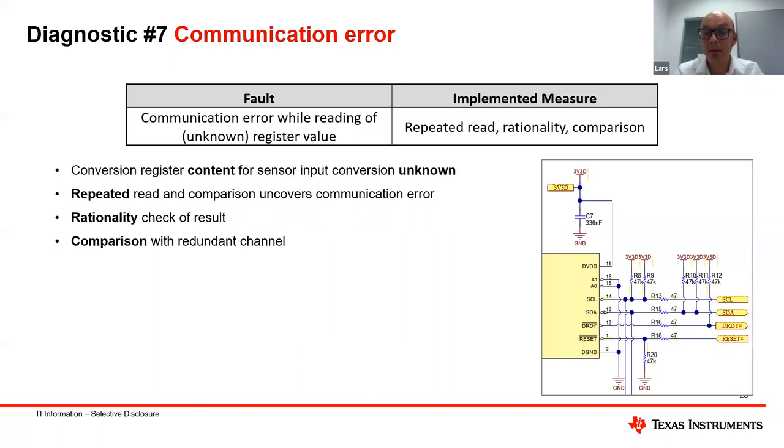So these are the important things you can do in order to make sure that the communication works. Of course, we also have A-to-D converters in our portfolio which have CRC protection both ways, which could also help. But in this case, it was not too important, and we could live without the CRC code at the end.